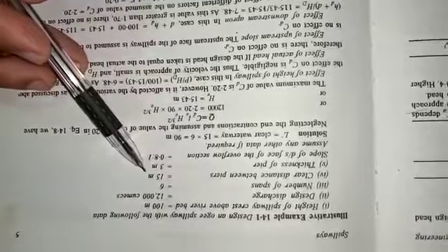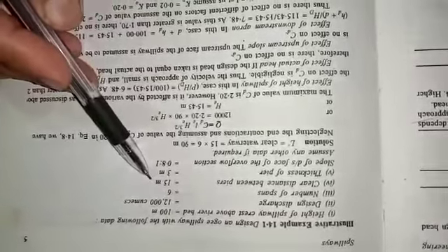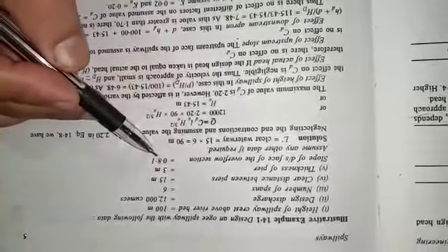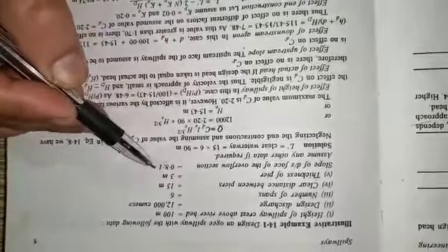The clear distance between the piers, that is the width of each span of the spillway, is 15 meters, and the thickness of the piers in between is 3 meters. The slope of the downstream face of the overflow section is given as 0.8 horizontal to 1 vertical.